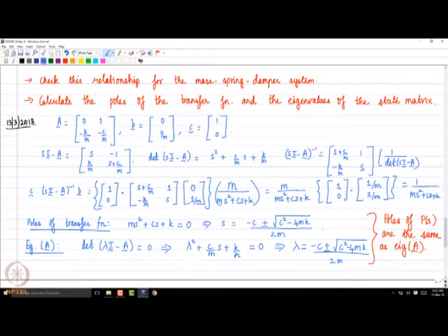So that's the inverse. Okay. So that is going to be sI minus A inverse, and C dot (sI minus A) inverse B is going to be this, and if you do the algebra, you will see that you will get the transfer function itself. So that's just an exercise to verify, or check the formula that we derived for this particular example. Obviously it must be true, right.